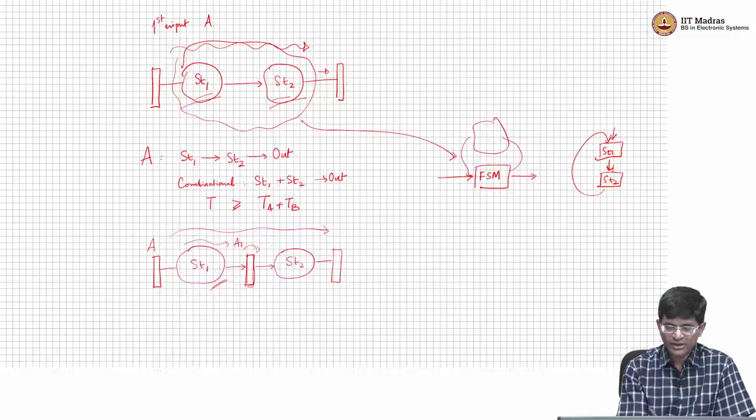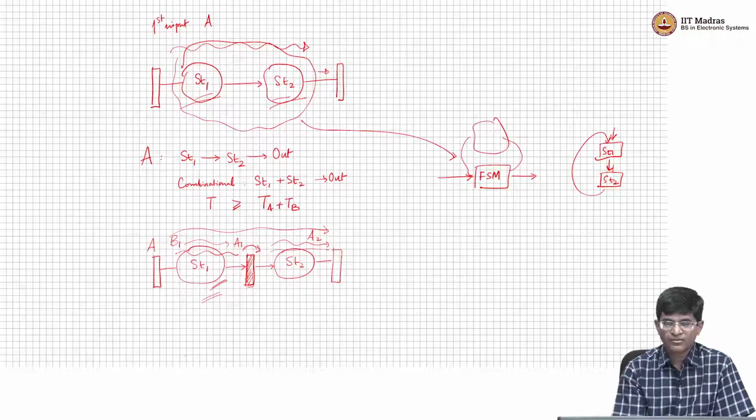That A1 will then sit over here and be ready for the computation of A2 in the next clock cycle. Now what has happened as a result of adding this new register is that the moment A1 has jumped across this register, I no longer care what's happening on the input side. And what that means is I can actually apply a new input, which I will call B1, at this point in time. B1 then goes through stage 1 while A1 is going through stage 2.